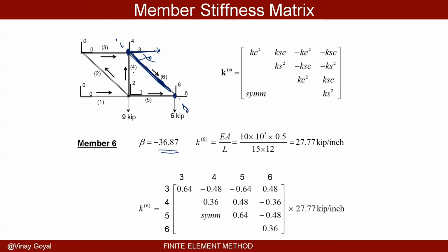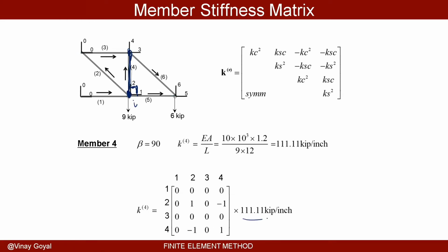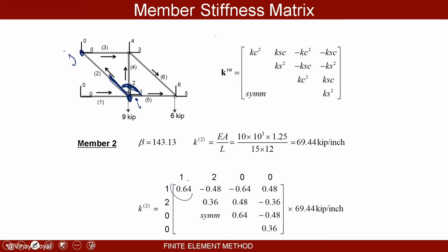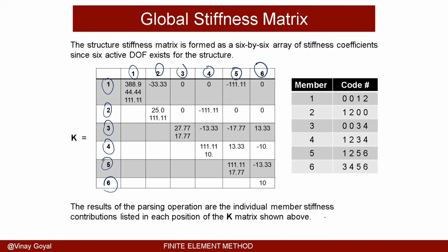So let's look at where 1 and 1 shows up. 1 and 1 does not show up here. It shows up here. 1 and 1 shows up here, and it shows up here. It shows up 3 times, so I can add it up. You can see that I added 3 of the instances there. And I can then do a search for every single one of them and add them up. Now you notice I kept this empty because the stiffness matrix for a conservative system will be symmetric, and this is a linear system. There's no reason to believe that it's not symmetric.